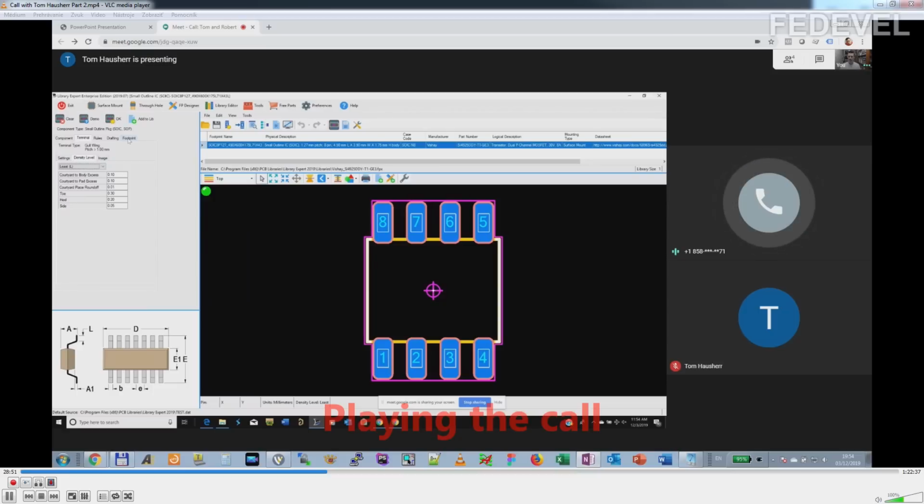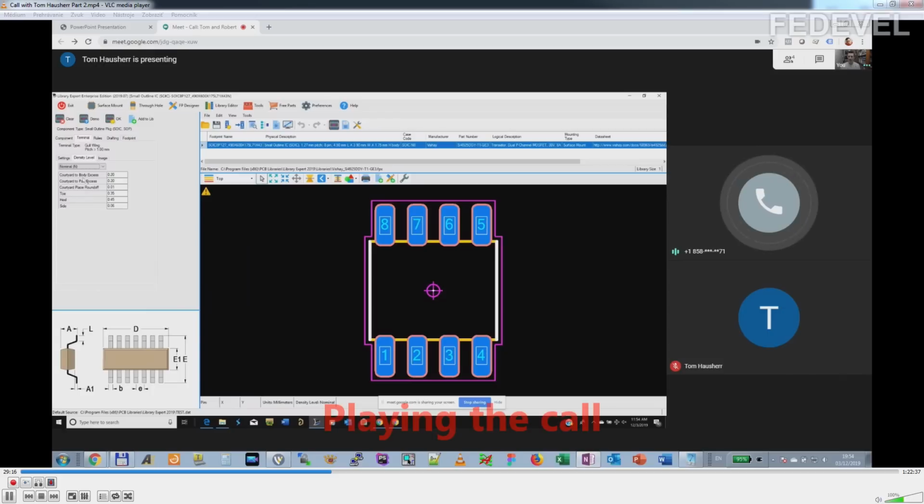And Dieter Bergman says, well, yeah, you're right. It could have a use only for hand soldering boards. If you're going to use your solder and your soldering iron in one hand and hand solder your boards, maybe you could use the most density level. And we're going to go ahead and put in the 7351C that the most density level is strictly applicable for hand soldering. And the nominal density level is the big one, mostly widely used by most people.